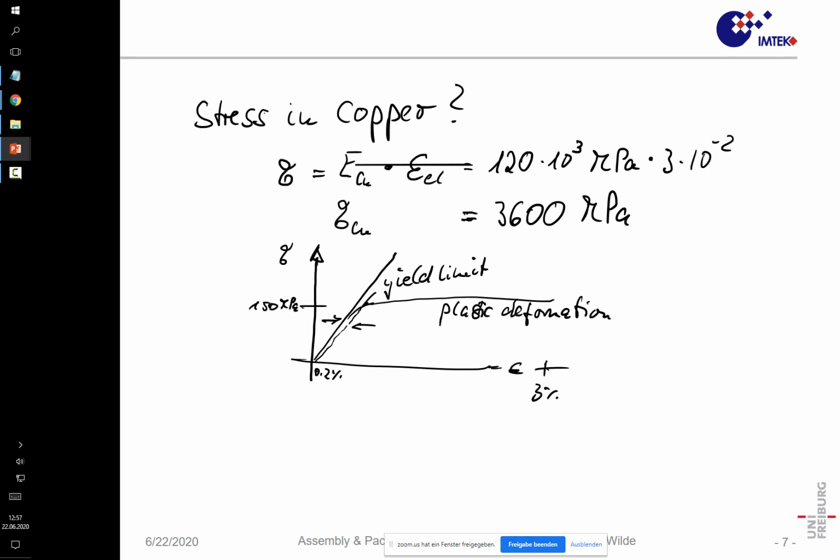So, okay. But on the other hand, we can see we have done an estimation. In fact, that was a very crude simplification. In our model, for instance, the thickness of a printed wiring board doesn't have an effect on the number of cycles to failure. In fact, that's not true. You could again say the bigger the part, or in this case, the thicker the part, the bigger the problem.